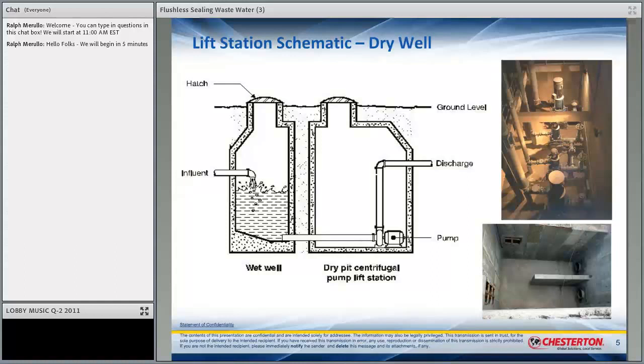So the water from the municipality flows into the lift station and it lifts it up. That's its purpose. One of the challenges in this area is that it's remote in many cases, so you may not have flush water. The challenge is, what happens if you face problems like fiber in the fluid? That fiber will collect in the pump and can cause issues for the seal. So how do you address that challenge? We're going to talk about this. These are some of the newer challenges that some municipalities face, not all.